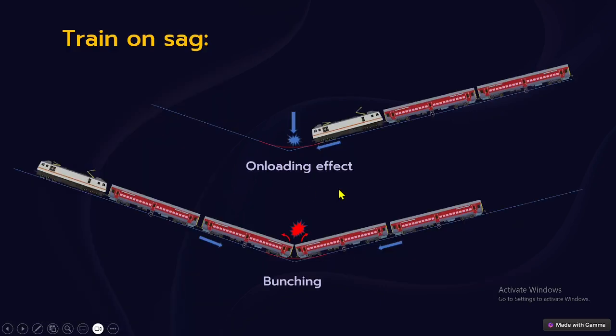And you can explain this diagrammatically. You see here, this is a train coming from the down gradient and passing over this sag. When it is coming, there will be more momentum. Because of that, there will be a centrifugal force acting downward here. Because of this, there will be more force on the rail. At the same time, the vehicle components will also be subjected to more force, the springs and axles also. There will also be discomfort because of the vertical, downward acceleration. That is why it is to be properly controlled by provision of a proper flat vertical curve as prescribed.